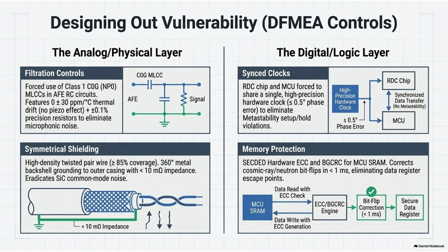And the factory doesn't just trust the digital curve. The specification demands a physical destructive pull test every single shift, proving that a completed crimp can withstand a minimum of 50 newtons of force before failing. The power connections also require extreme process controls. For the high current bus bars, the enemy is joule heating.